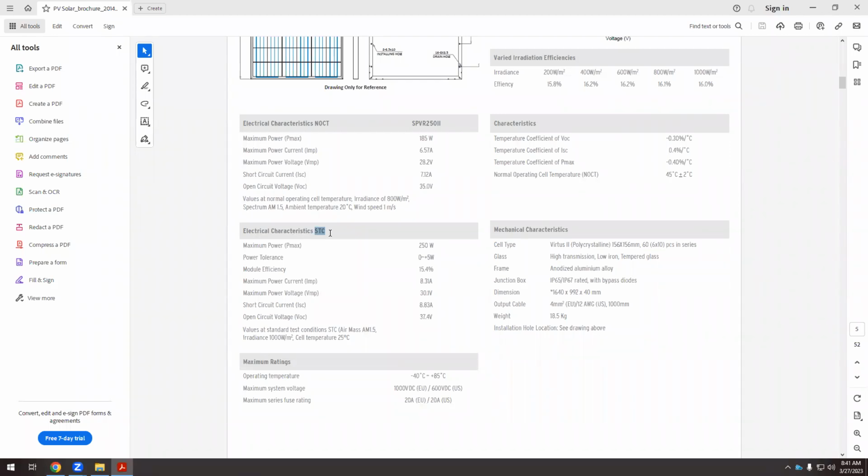It's a perfect solar irradiance without any clouds, without any pollution, with the right temperature for the cell. Basically we have these two things, the solar irradiance and the cell temperature. So this is the maximum production that we can have under the best circumstances, these standard test conditions.